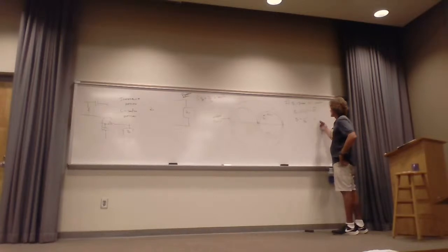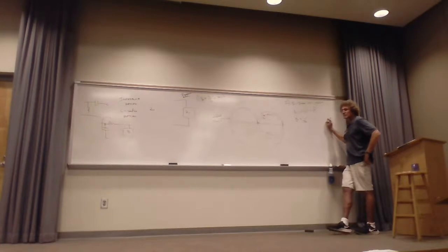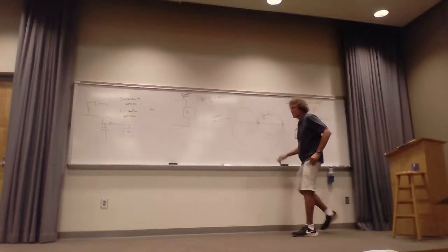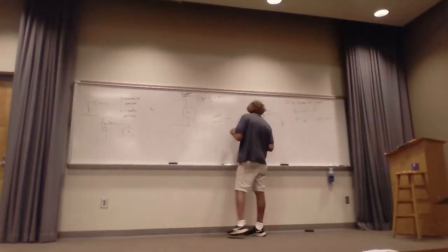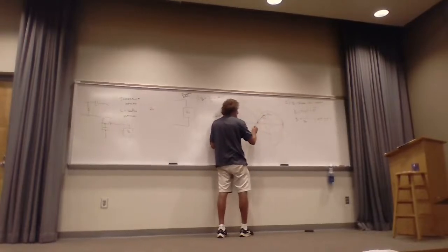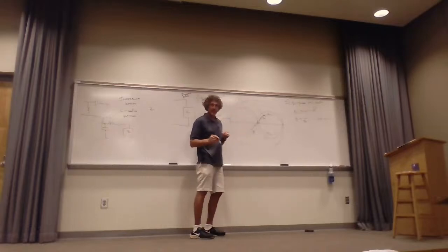Anyway, I want it in real and imaginary. So it's 0.4 minus J0.2. All right, 0.4 minus J0.2. The way you get this point here is you just go through the conjugate point, draw a circle. If that's ZL, this would be YL, correct, class?